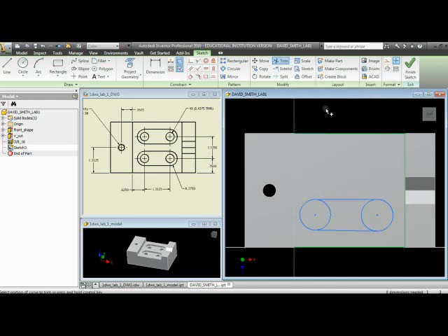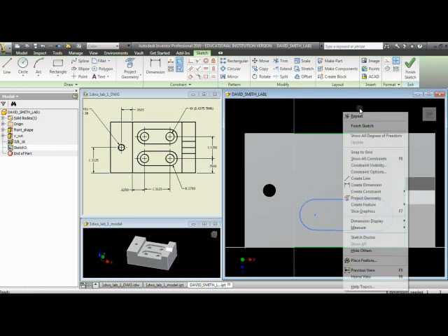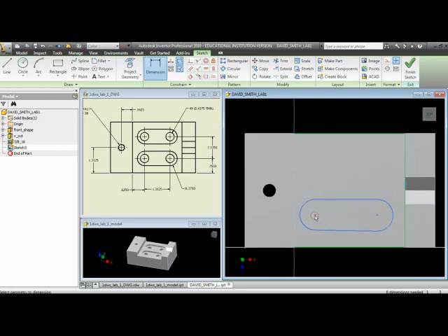Okay. Once I get that done, then I can trim out this portion of this circle and this portion of the circle to make arcs. You can hit the trim key up here, or note you can hit the X on your keyboard. Doesn't matter. The trim command works a little bit different than your regular AutoCAD in the fact that as long as there are some lines and things that intersect, if you touch that particular object where you want it to go away and click it, it will go away. So I just have to click it, move on, and that's done. I'll right click, done, or I could hit the escape key, it wouldn't matter.